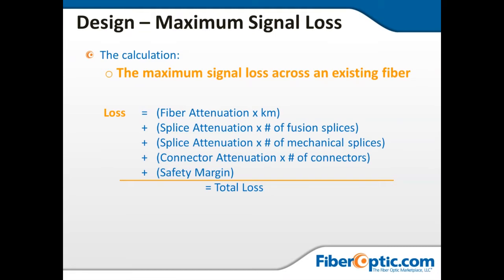Fortunately for us in the physical plant world, it's a pretty simple calculation, or what I say, easy math. The fiber itself, or the light traveling through the glass, is really the only component of our physical plant that is wavelength sensitive and is based on your design. Currently, if I were transmitting at 1310, just one of the options that I have, the loss could be as much as a half a dB per kilometer of distance. But the same fiber at 1550 would be more like 0.22. In fact, at 1310, most fibers today are really running around 0.35 dB per kilometer.